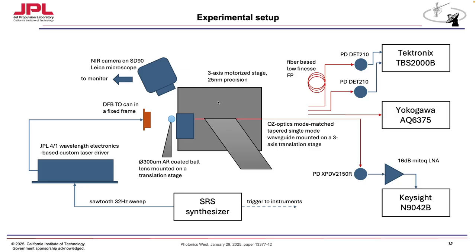For those who don't know, if we have a laser, and we take another laser and shine it into our laser, we can lock one laser to the other. It's the so-called master-slave configuration. It is known for a long time for all oscillators. In this particular case, we just shine light into a microcavity. It's just a microchip, and it reflects back, and it locks the laser to the microring, and it keeps the frequency of the laser from drifting with respect to the cavity mode.